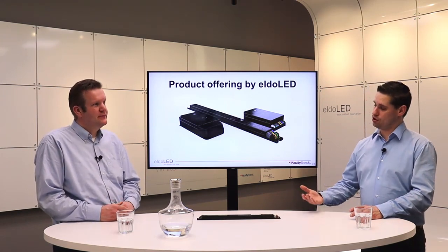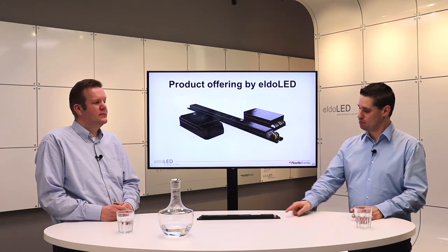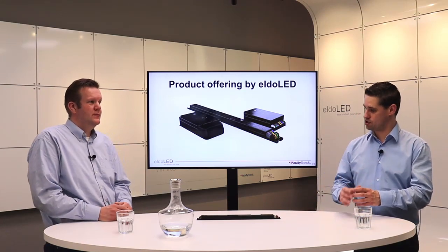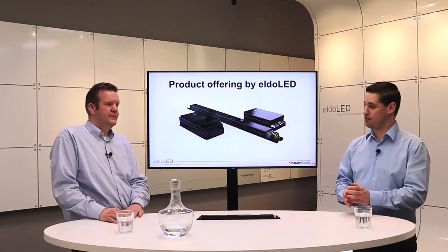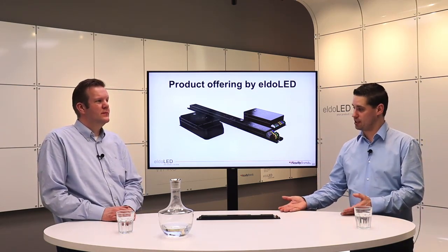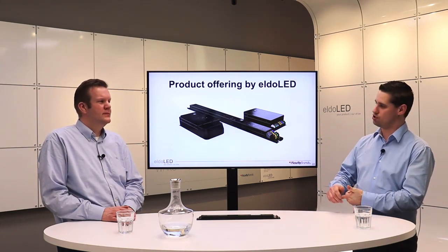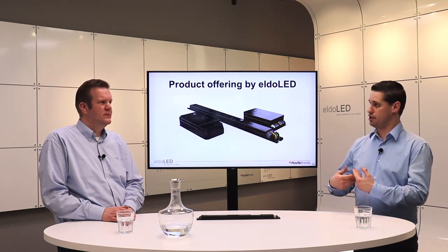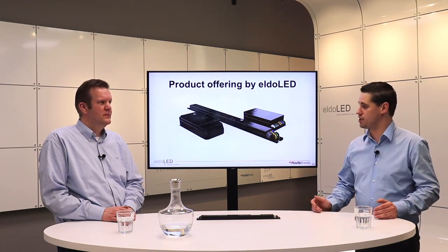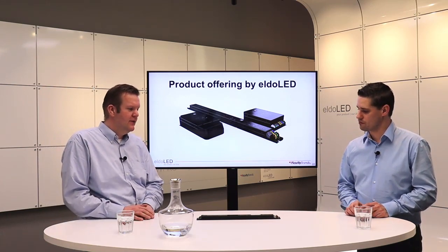Yeah, but you can also do the opposite. You can also say to the driver, I only want to use one DMX address, but I want to connect it to all 4 outputs. Okay. So I can connect 4 LED light sources to that single driver and act as if it's just a 1-channel DMX product. With that versatility in programming, there's no reason to have a 3-channel or 2-channel product available anymore. It's just the amount of power that the device is supplying, and the maximum allowed number of channels is 4. Got it. And how many terminals are on that driver then for DMX?